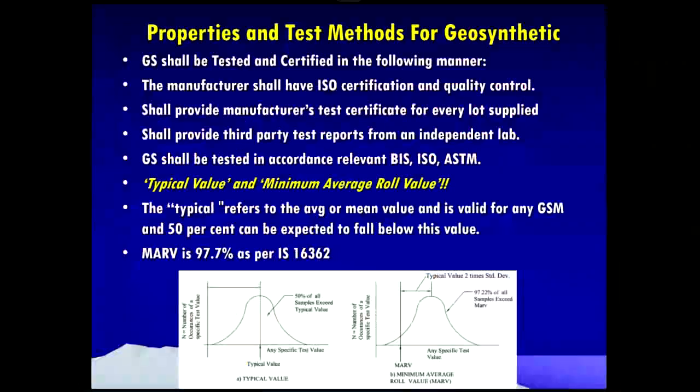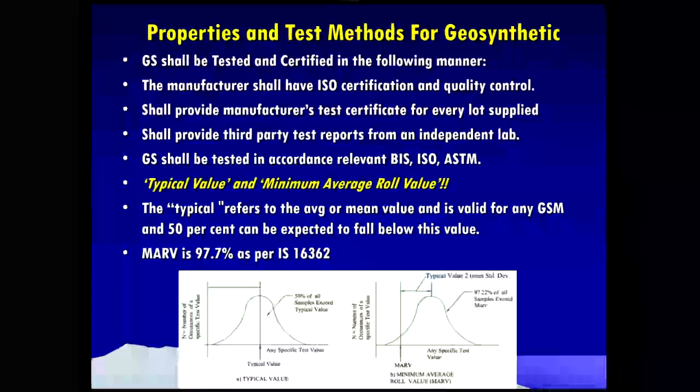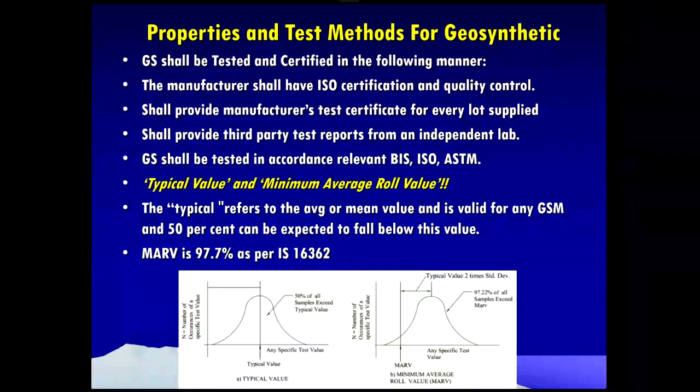Now, recently, as I told you, IRC SP 59 2019 has a record on the usage of geosynthetics in pavements. I'll share the code of practice with you. You can go through these things. They are all given: what should be the properties, what are the test methods, what are the various acceptable quality controls. This is self-explanatory.